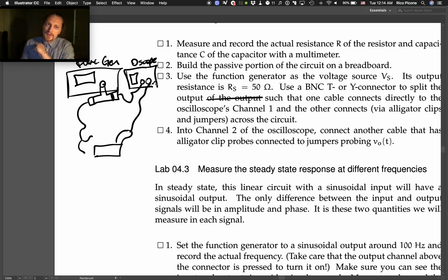Probably can just use AC coupling on both channels. Make sure you don't have one of the oscilloscopes, I was in there the other day, or today actually, and well, I guess technically yesterday. Anyways, there was a 10x probe setting set on the two channels.